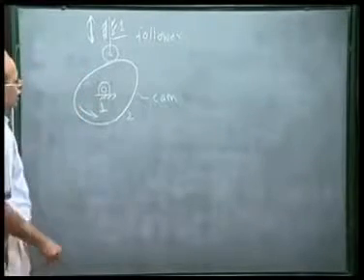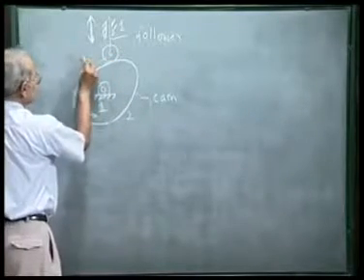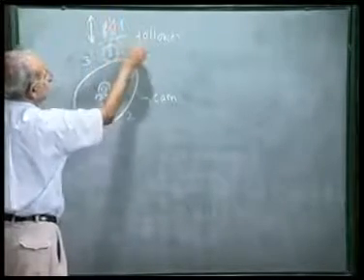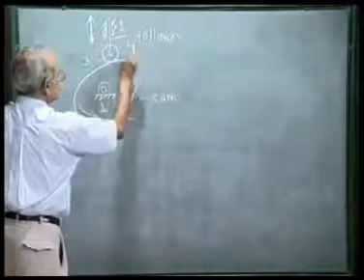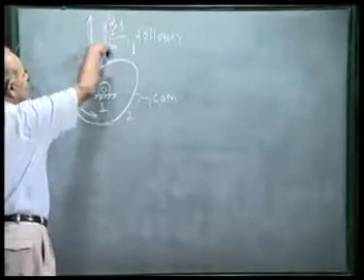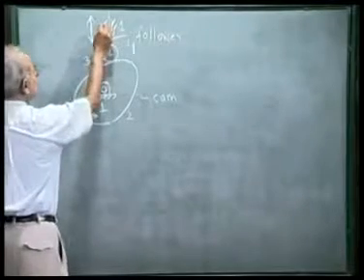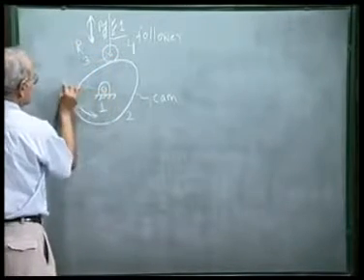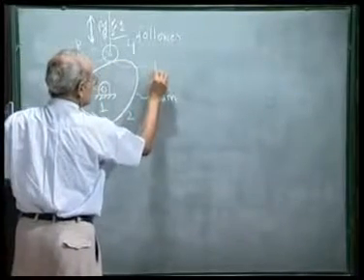So this is again a 4-link mechanism. Fixed link number 1, cam is 2, this roller is 3, and this roller has a revolute pair with this output member or the follower, which I call 4. So uniform rotary motion of this cam will give rectilinear oscillation of the follower along the guide. This is a prismatic pair. There is a revolute pair, there is a revolute pair, and between 2 and 3 we have a line contact, which is a higher pair.